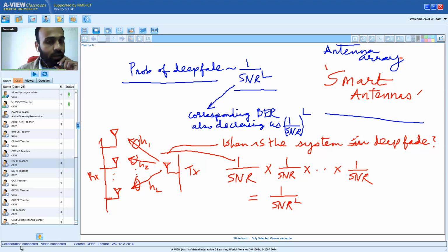Digital beamforming, yeah, this is exactly digital beamforming. Digital beamforming is basically beamforming in a particular direction. This is also electronic beamforming, that is not physically steering an array. What we do in digital beamforming is we don't physically steer the array in a particular direction, but using the antenna weights we choose a particular direction. The theory is a bit more involved. I don't know if I'll be able to cover that theory, but digital beamforming or electronic beamforming means rather than steering the array physically, you are using electronic weights to basically choose a particular direction.